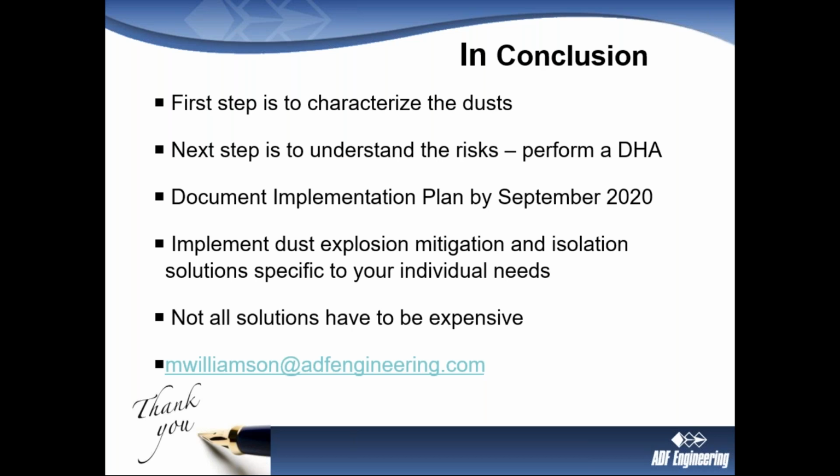Okay, thank you. Our next question is, is sugar considered an explosive dust? Absolutely. I personally have done DHAs on sugar facilities. And sugar, as you may know if you're familiar with it, is a very, very friable material, especially when you're doing pneumatic conveying with sugar. You're going to find it breaks down into powdered sugar very, very easily.